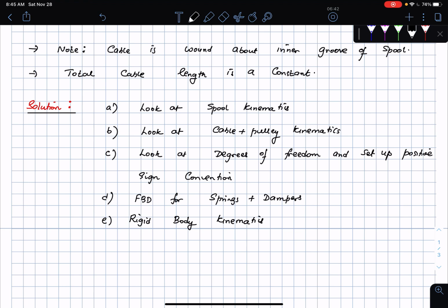Once I have these, the first thing I typically do is the kinematics, because the kinematics lets me get more confident in terms of how to solve the problem, and it's obviously good to get the kinematics done first, because you're going to need that information to do the kinetics. There are some people who will just directly start drawing the free body diagrams, but that is not my style. Okay, all right, so let's look at what's going to be happening here.